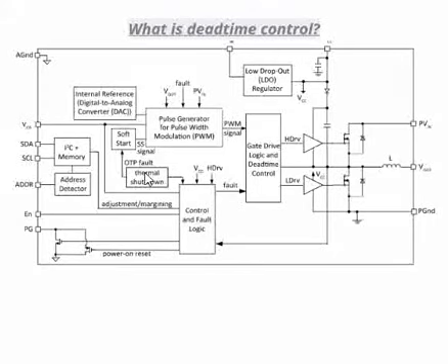Hello all, what you see here is a block diagram of a DC-DC converter where you have the power supply and you have the PWM generation and you have the MOSFETs configuration here. So we are going to know about something called dead time control. If you see here in the configuration, for the high drive of the MOSFET and low drive of the MOSFET, there is a block which says gate drive logic, which is clearly understood, and dead time control. What is this dead time control?